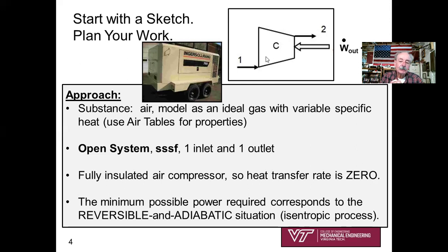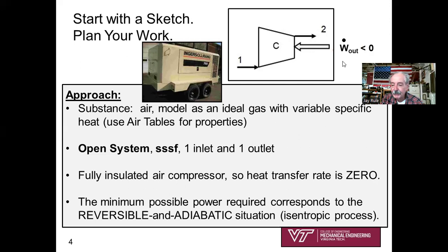I haven't shown heat transfer on my sketch because we're going to say that this compressor is fully insulated, but I am showing W dot out from the open system is less than 0. Let me drag my picture down here. W dot out is less than 0. In other words, power is required to drive the compressor.